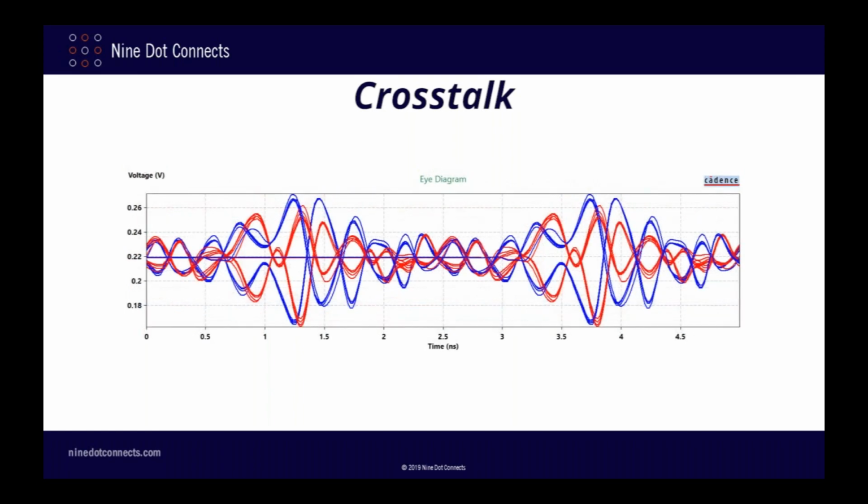If we overlay the two address 12 traces from each simulation, we do see that the one with excessive parallelism, here shown in blue, actually is a bit worse, but not by very much. I think the main reason why this is so is that we have relatively slow signal slew rates on our transitions, combined with the fact that these signals are well terminated and of relatively short lengths. The crosstalk noise just doesn't build up enough to cause problems.